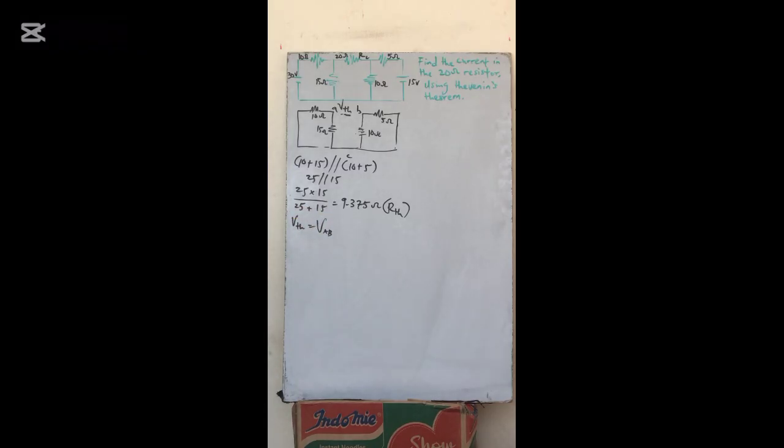And so now we need the voltage here and the voltage here before we can get AB. So from that view, we are going to have the current IA and the current IB. So how do we get that? Current A is equal to the voltage over the equivalent resistance. That means there's an equivalent resistance in this place and an equivalent resistance in this place.